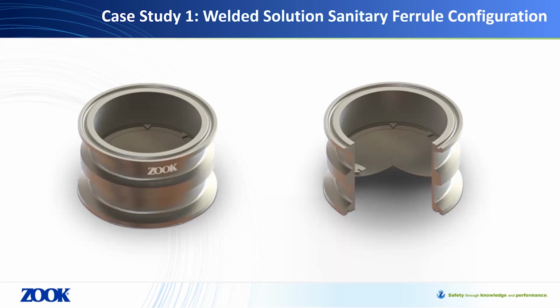The rupture disc solution needed to function properly in a sanitary environment, but required a very stringent helium leak rate on both the process and atmospheric sides of the disc. By replacing the traditional rupture disc with a welded solution immediately upstream of the valve, the client now has the ability to test the valve by pressurizing the area between the rupture disc and the valve, allowing for the functionality of the valve to be validated while not interfering with the rest of the system.